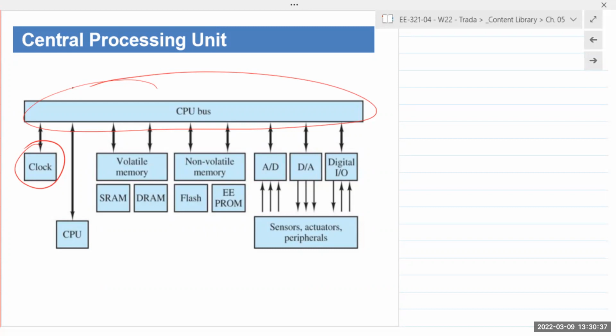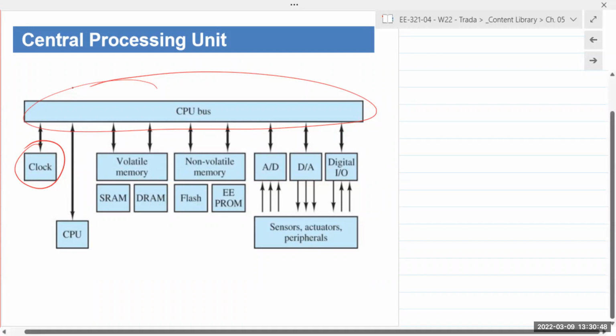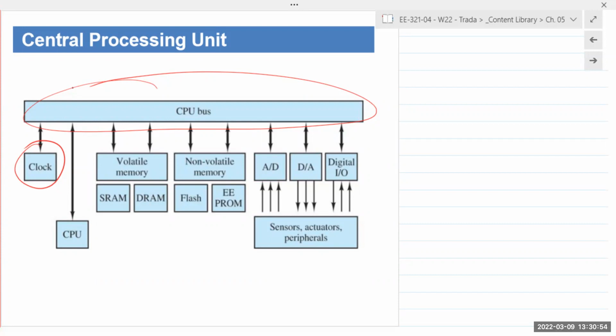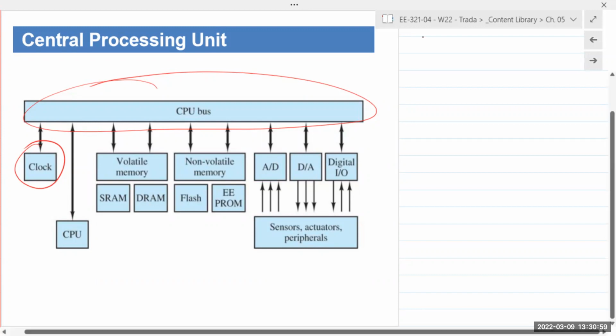Initially, the first processor in the world was the 4004 from Intel. It was a 4-bit processor. Then came an 8-bit processor, a 16-bit, then 32-bit CPUs. And then a few years ago, we moved to 64 bits. So the CPU bus is 64 lines of addressable memory. The reason we all moved to 64-bit is because access to memory locations is in binary form, 2 raised to n. If it's a 32-bit system and n is equal to 32, you can only access a maximum of 4 GB of RAM.